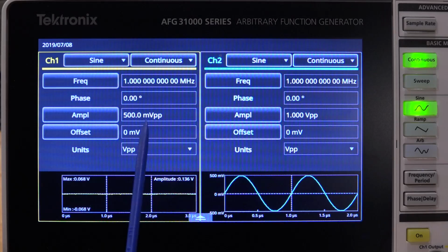Now both of these are below the threshold for which that impedance begins to matter. The signal amplitude is too small, the diode cannot turn on, so we don't have any nonlinear effect, and the frequency is low, and the capacitance doesn't really do anything. So therefore, we would expect the signal displayed here to match very closely to what is supposed to be actually applied, even if we didn't have any measurement capability directly on the DUT.